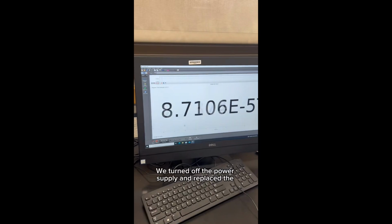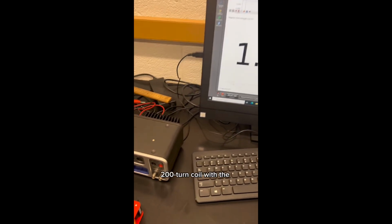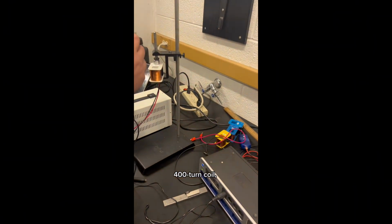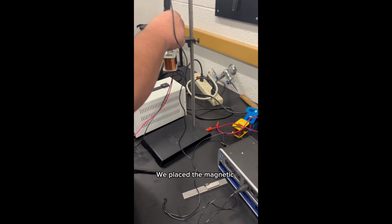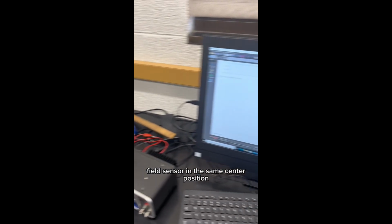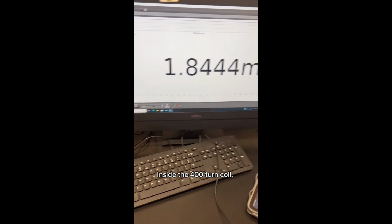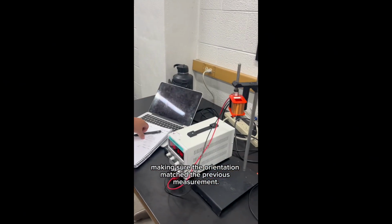We turned off the power supply and replaced the 200-turn coil with the 400-turn coil, keeping the rest of the setup unchanged. We placed the magnetic field sensor in the same center position inside the 400-turn coil, making sure the orientation matched the previous measurement.